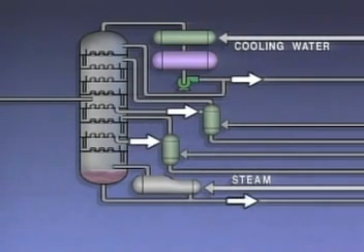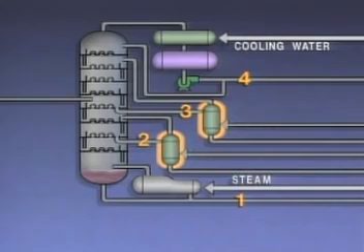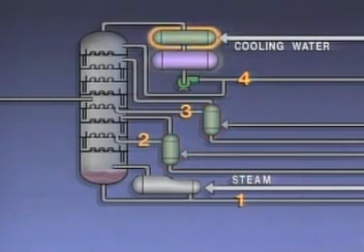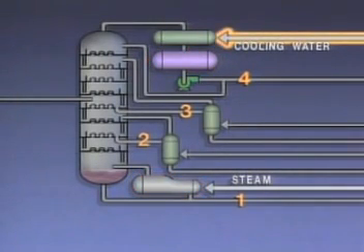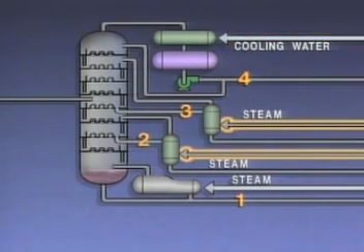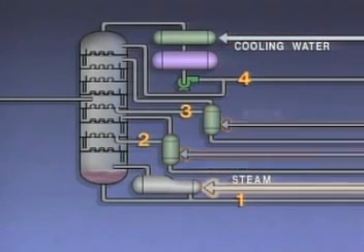Each product may be made up of one or more substances. The tower has four draw-off lines located at different levels. The draw-off lines provide a means for removing the products of the distillation. We'll number the products 1 through 4 to identify them. The illustration also shows two devices called strippers or side stream strippers: a condenser, a receiver, and a reboiler. Cooling water reaches the condenser through this line. Steam reaches the strippers through these two lines. And steam reaches the reboiler through this line.